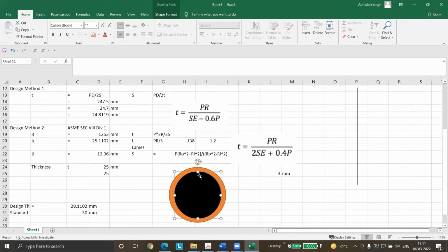So when the vessel is corroded, which is going to happen, it should still have a thickness equal to the design thickness, the minimum thickness I need to take care of this 20 bar pressure, right? Because the vessel should not fail after corrosion, knowing that 3 mm is going to corrode. So I have to design for end of life, right? If I design for start of life, then we know that we are going to fail, isn't it?